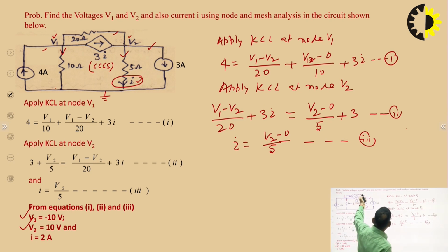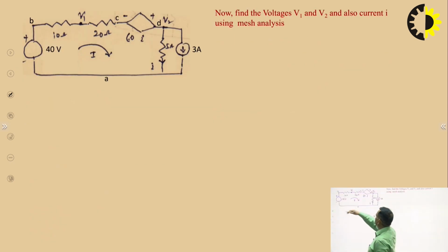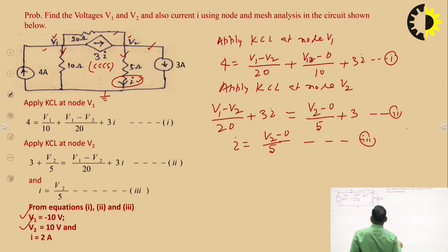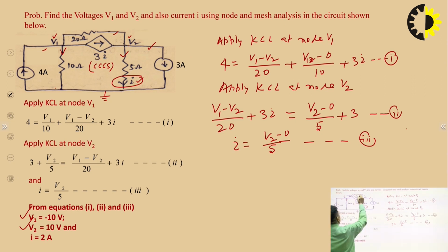Now solve this circuit using mesh analysis. This circuit is very much suitable for node analysis. To apply mesh analysis, we modify the circuit as per our convenience, so that we are able to apply Kirchhoff's voltage law. So we can carry out the source transformation of this branch.